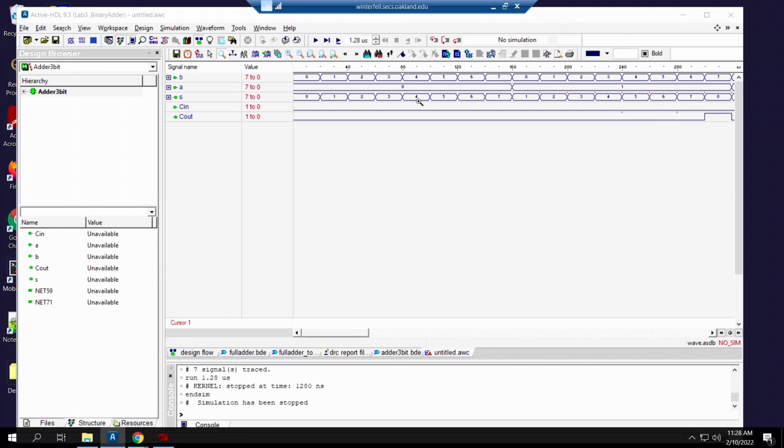So from 0 to 7, that's 8 times or 8 cycles. 8 times 20 is 160 nanoseconds, and that's why we set A to 160 nanoseconds. So as you can see here, from the beginning we have 0 to 7, and then all of that with A being 0. When they start repeating, or the cycle starts to return, the A is incremented to 1.